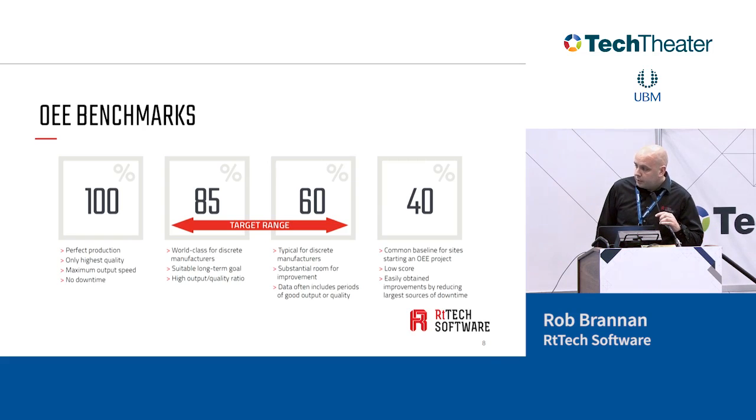If I'm honest, if companies are doing OEE manually to begin with, they tend to be producing a higher figure, maybe up towards the 80–85% mark. And the reason for that really is the granularity of information that they're capturing. If people are capturing downtime information, performance information manually on bits of paper or spreadsheets, then realistically they're only going to be able to capture, say, 10-minute buckets at a time. So those tiny stoppages that are occurring, operators won't be collecting that information. Using spreadsheets and bits of paper to capture information is just not viable for them.